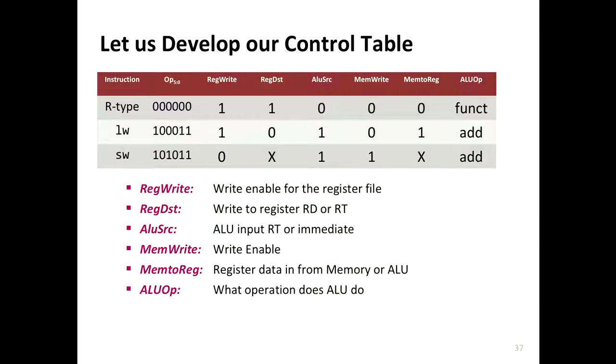Store word, very similar. You're not going to do a write operation into the register. Your source is still coming in from the immediate value, and you're going to do a memory write operation. So you have all these 3 values enabled. And these will actually enable you to almost implement the ITAP instructions. And this kind of forms the control unit part of the whole architecture.